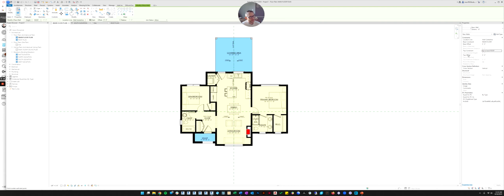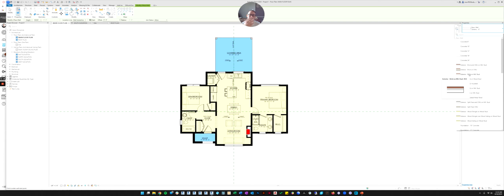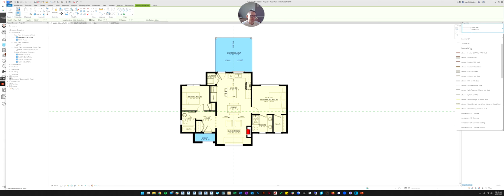The other thing you might want to pay attention to is this top area. This is telling you what type of wall you're going to create. Right now, it's just saying we're creating a generic 8-inch wall. So if you click this, here are the other walls that are available in the template. These are just walls that someone created already for you and put into the template. These are all examples of family types. A wall is a system family, and inside the system family, these are all the different types. And you can create your own type, which we will do later in this exercise.